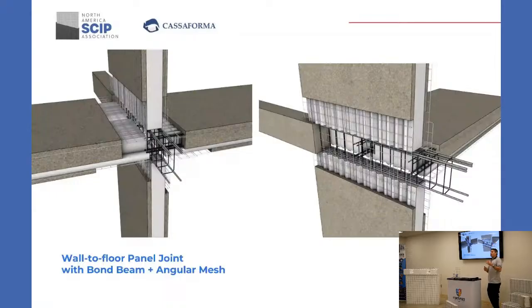The longer the span is, the more stiffness I require here on the connection. So this is probably a good connection for panels that have joists on them, which probably implies they are very large and therefore receiving a lot of load. The same comes for this.